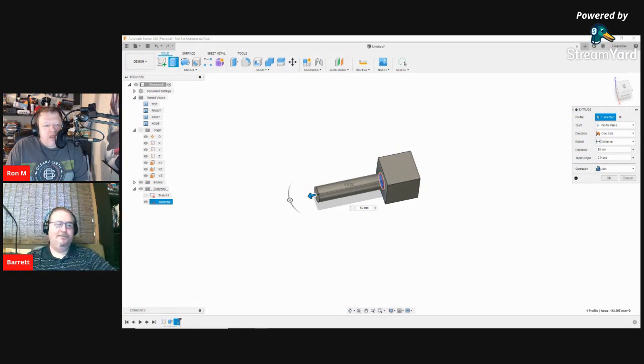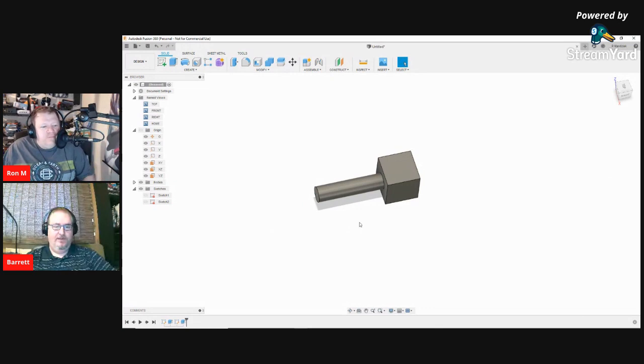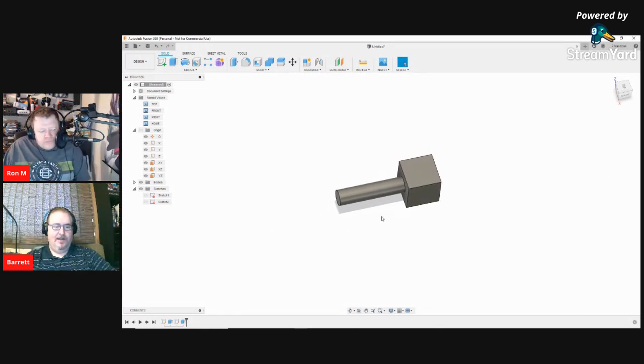It's an option. Okay. So now that I'm thinking of this, say I'm looking at this and I go, oh dear, I want that to be sticking out 50, but I made a mistake on the block. I want it to be a rectangle. How does someone go back to fix that? Okay. Well, first off, let's finish this by clicking OK and exiting out of that. If you want to go back and modify the rectangle, down at the bottom there's two ways that you can access this.